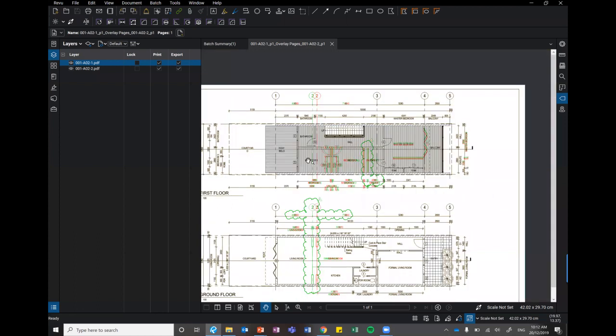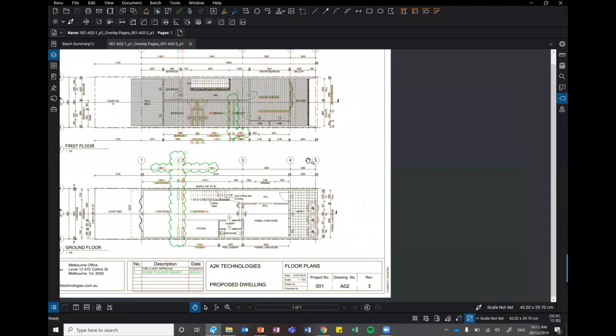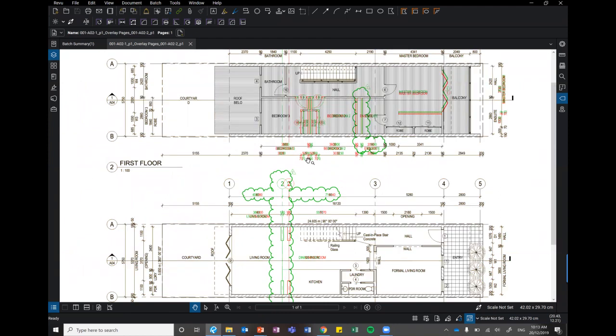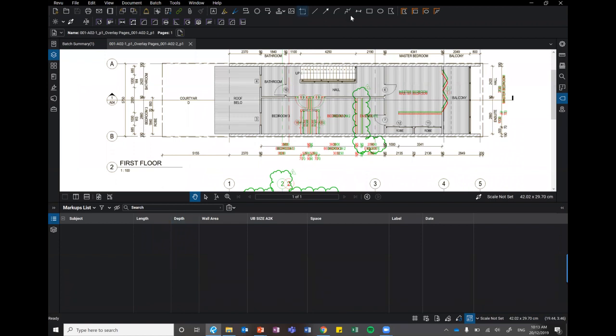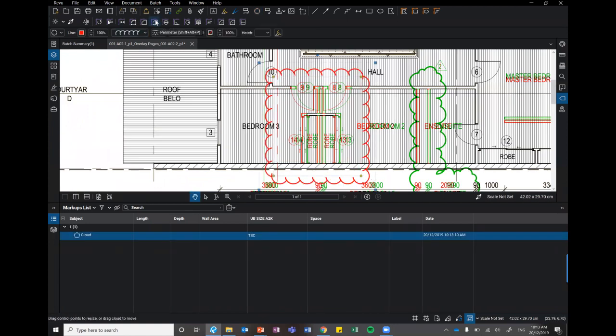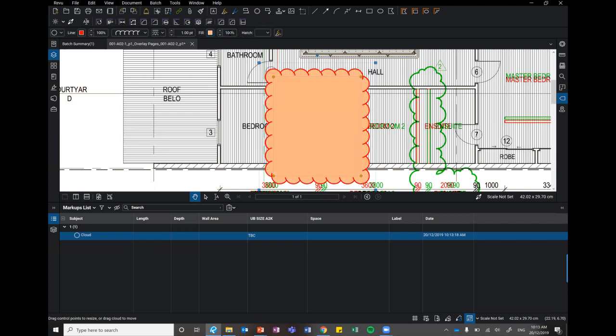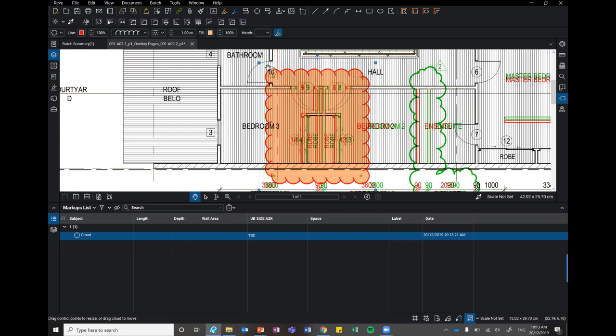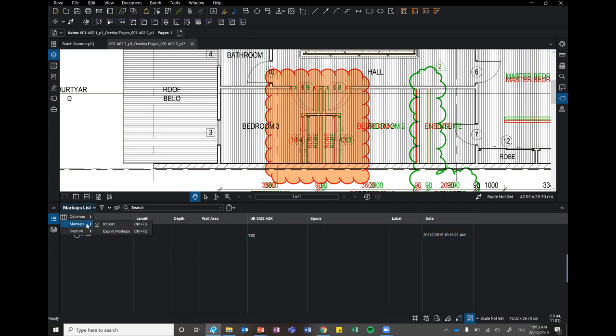This is a really great process to speed things up. We could also use this with the clouding tool. And interesting enough, down in the bottom of Bluebeam, if I just throw in a regular cloud, say we did a compare documents and we had a clouding option, I'm just going to turn this on to highlight. All this information will come through in all the clouds. We can export the markups, and you can import that into another file.